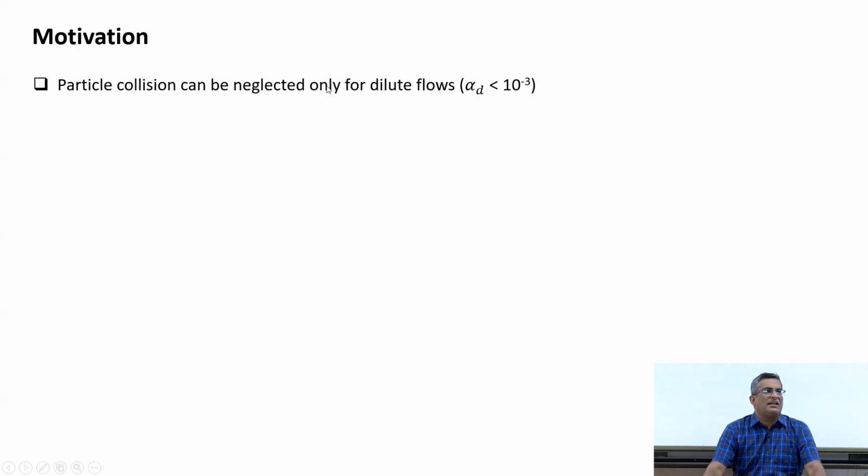So, in that case we can have very dilute flows where the volume fraction is between 10 to the power minus 6 and 10 to the power minus 3, where we have two-way coupling, but the collision is not important.